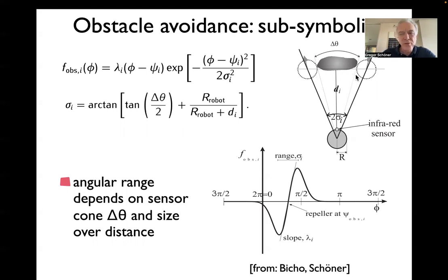But then you have to avoid that whole sector, and that will mean that when you're at the sense distance, your vehicle has to fit here. So it would be like half your vehicle width would be added here at this end, and half of it would be added here at that end. And that makes that cone actually, again, distance dependent, because the safety margin in angle that you need depends on how far the obstacle is.